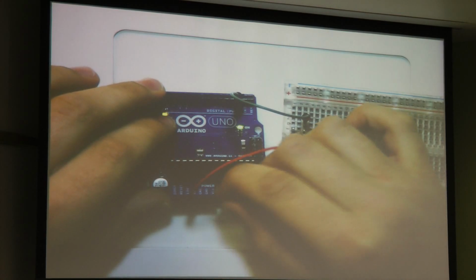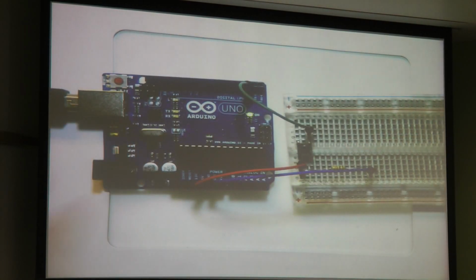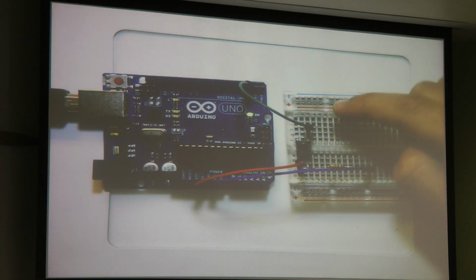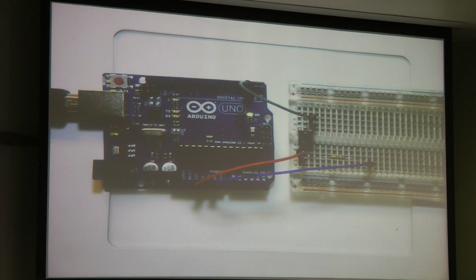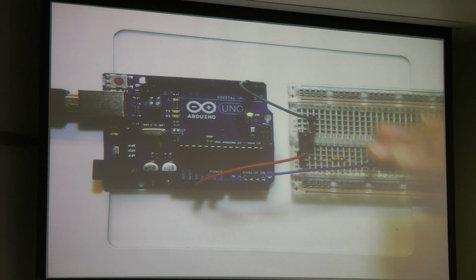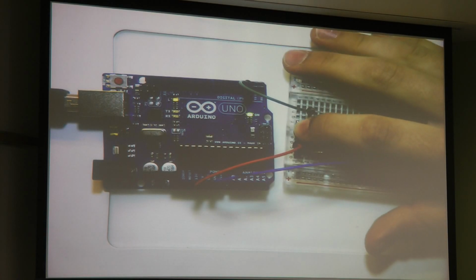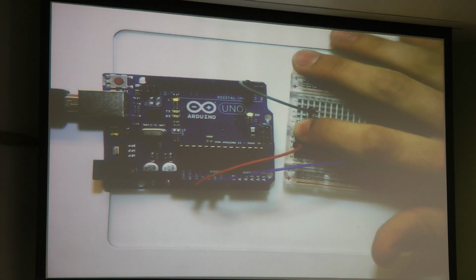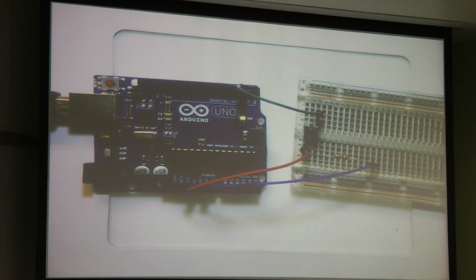So now what will happen is if any noise gets in, because these wires are really long, they act like antennas, and even if you use short wires it'll still happen, so this is a good design. Any noise that gets in won't have enough power to keep the pin higher than about 3 volts, even with the resistor connecting it to ground. The 5 volt rail can do that fine and the LED goes on here. But noise can't do it. So now we've just gotten rid of our noise.